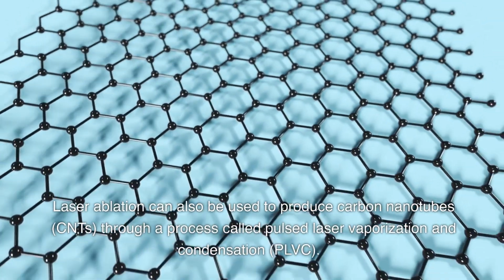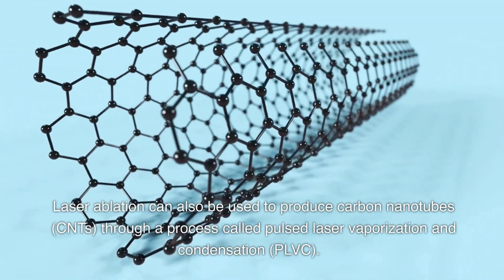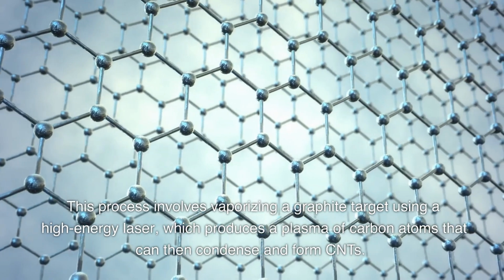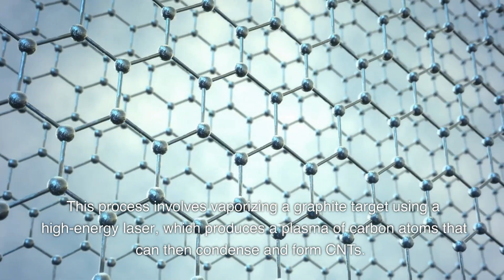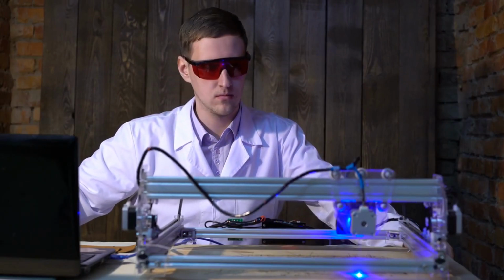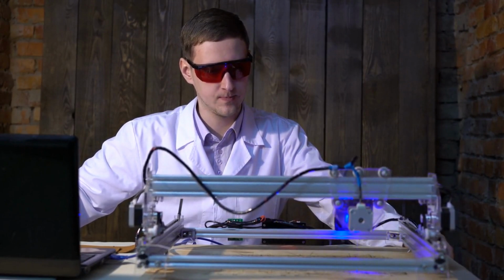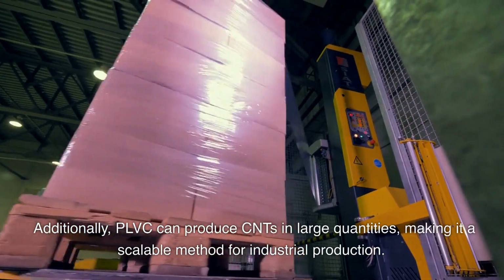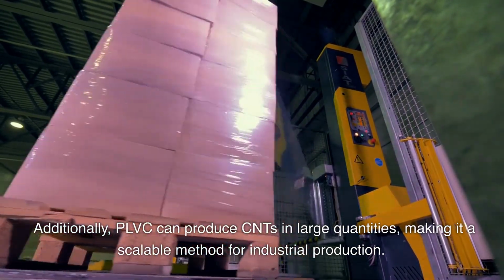Laser ablation can also be used to produce carbon nanotubes, CNTs, through a process called pulsed laser vaporization and condensation, PLVC. This process involves vaporizing a graphite target using a high-energy laser, which produces a plasma of carbon atoms that can then condense and form CNTs. The PLVC method for CNT production has several advantages over other methods, including the ability to produce high-quality CNTs with a high degree of purity and uniformity. Additionally, PLVC can produce CNTs in large quantities, making it a scalable method for industrial production.